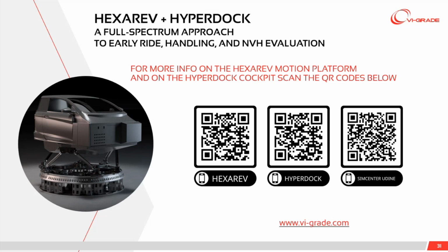So if your multi-body vehicle model has the engine mounts, and of course those are affecting the accelerations at the touch point, then you will be able to evaluate different mounts by running different simulations.